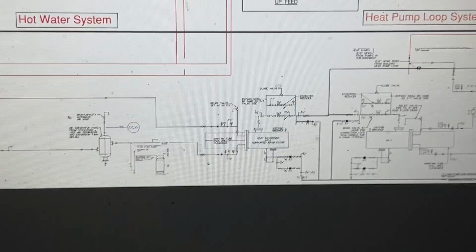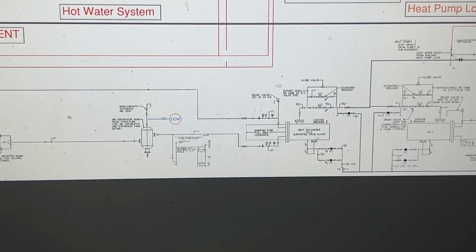To accommodate for the gravity on that, if we have about 46 feet there to our inline pumps, you're somewhere around a 20 to 25 psi system. So again, the relief on that system, if it ever climbed to 60 psi, there's a relief valve that will get run to a floor drain so that it would relieve itself.